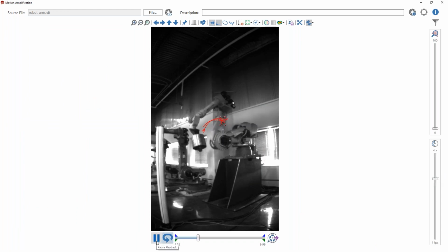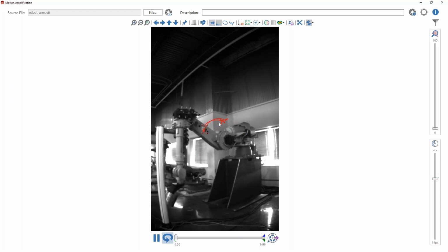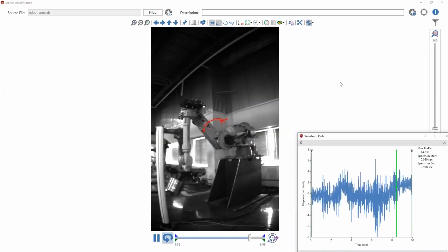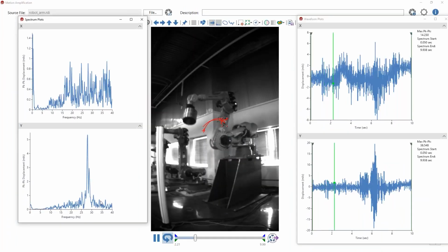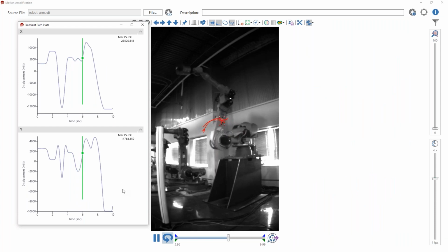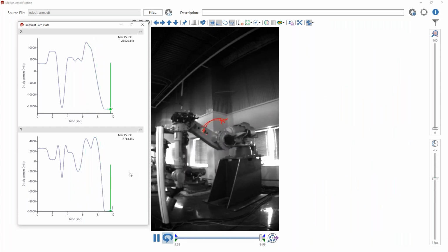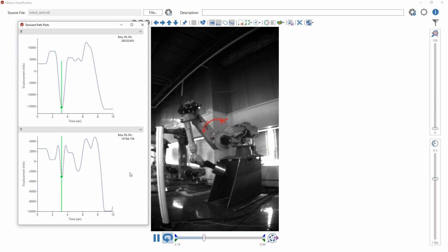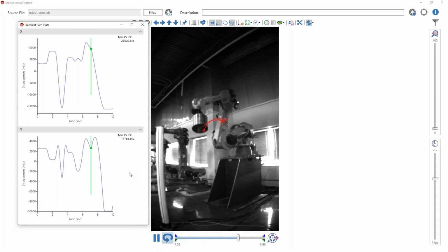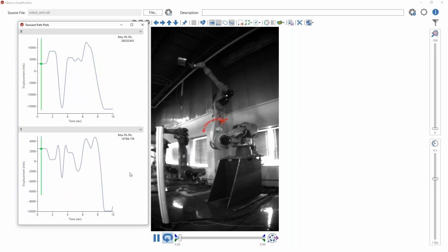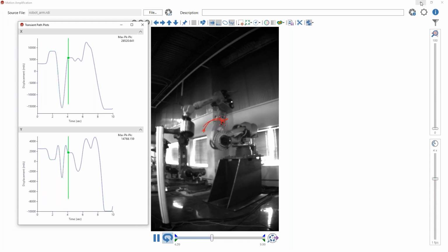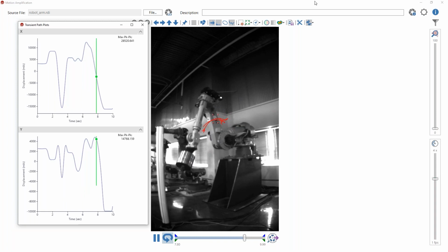This type of measurement allows you to track an object through a scene and show you what the motion looks like, right? So this motion is overlaid on this, and you can actually see it, and you can pull out information. You can pull out information that occurs, the overall motion, or you can pull out information that occurs inside that box, and then also spectral data from inside that box. And then of course you can show the overall motion too. But this goes beyond traditional motion amplification. Really, we're leveraging the fact that we can see objects transiting and measure them, right? And so the idea here is, again, leveraging the camera. You can get spectrum from moving objects this way.